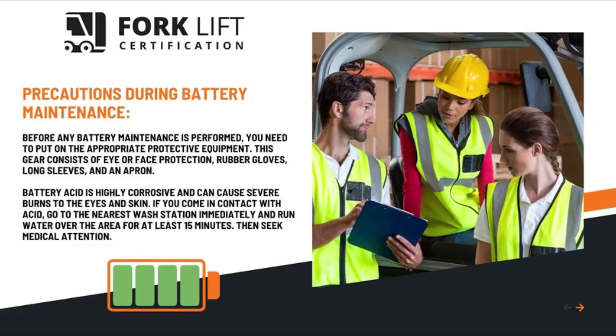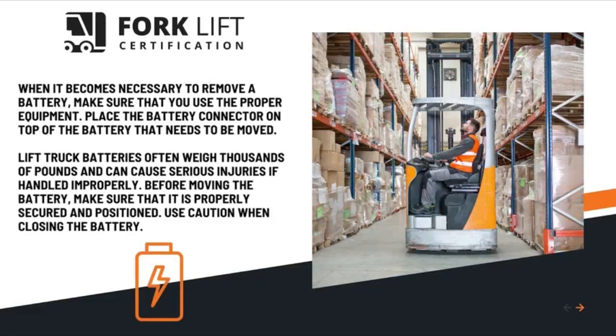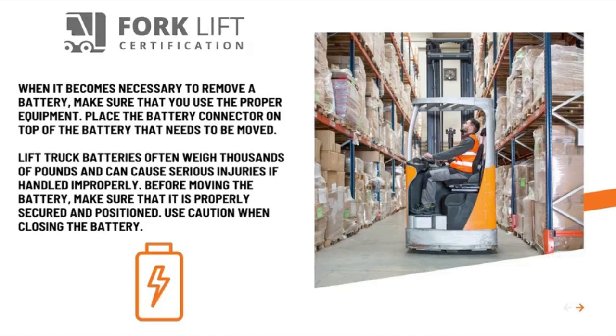Then seek medical attention. When it becomes necessary to remove a battery, make sure that you use the proper equipment. Place the battery connector on top of the battery that needs to be moved. Lift truck batteries often weigh thousands of pounds and can cause serious injuries if handled improperly. Before moving the battery, make sure that it is properly secured and positioned. Use caution when closing the battery.